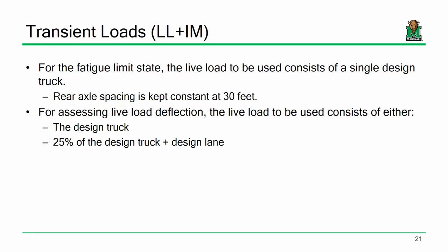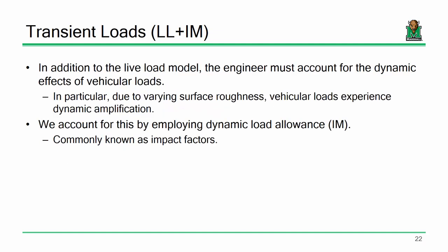When we do live load deflection checks, we use either the truck or 25% of the truck plus the lane. And that's just the code specified provisions for preventing exceeding maximum allowable deflection. So the truck or the 25% of the truck plus the lane.